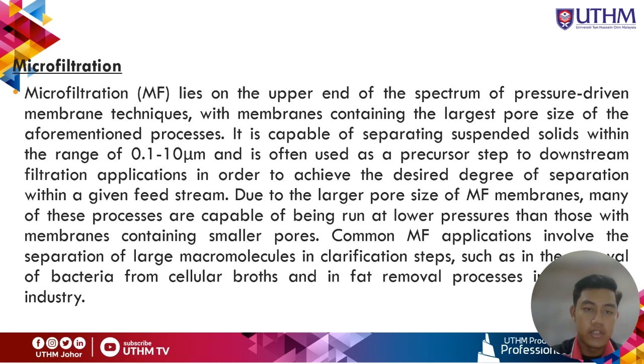Microfiltration lies on the upper end of the spectrum of pressure-driven membrane techniques, with membranes containing the largest pore size of the aforementioned processes. It is capable of separating suspended solids within the range of 0.1 up to 10 micrometers, and is often used as a precursor step to downstream filtration applications in order to achieve the desired degree of separation within a given feed stream.